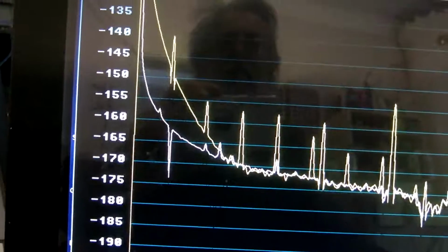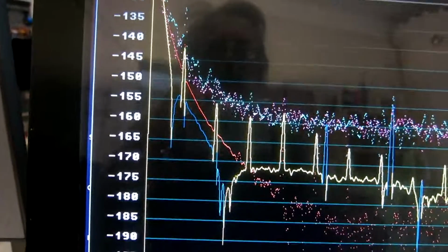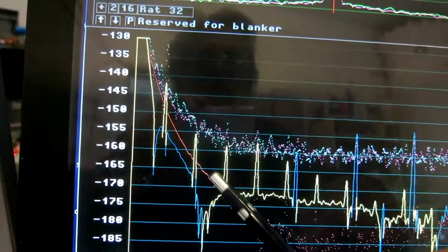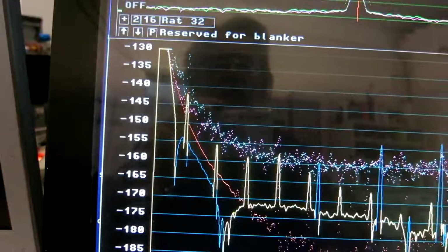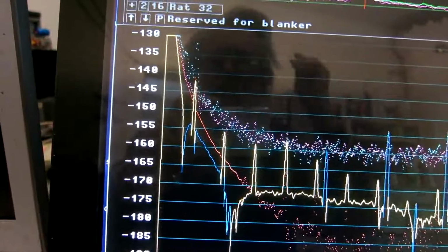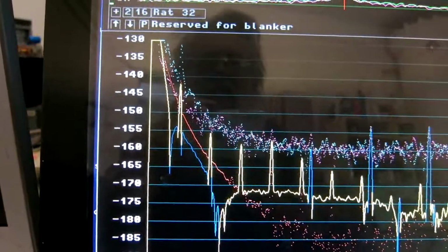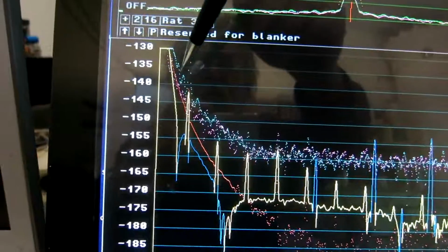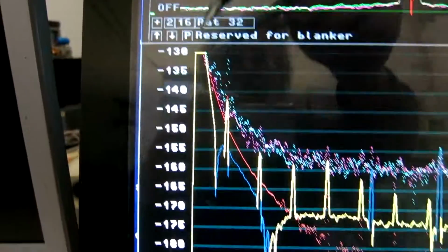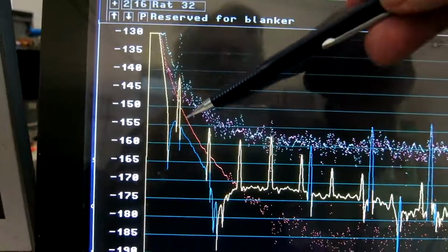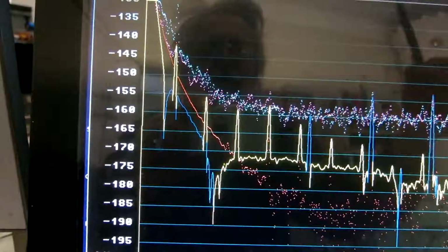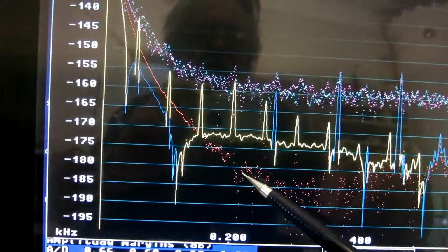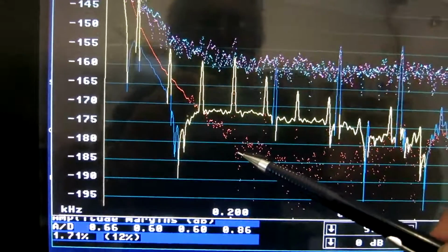I look at the details of phase noise here, and we can see that the sign of the real part is negative here. The imaginary part is even stronger than the real part. PLL means that one oscillator is following the other. At very small frequency offsets, they should be identical and there should be no correlation advantage at all. That's what we are approaching here, very close. And then at higher frequencies, the RC link is doing more and more filtering. And we can see how this curve here goes down into the noise at minus 180, somewhere around 200 Hertz.